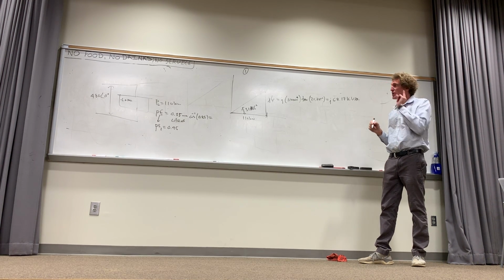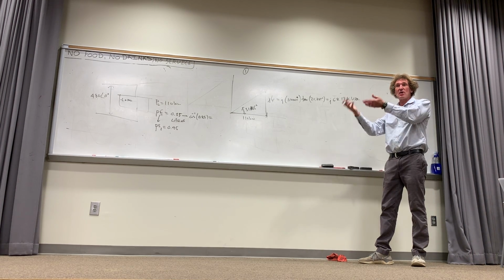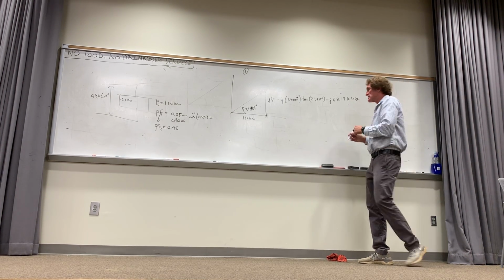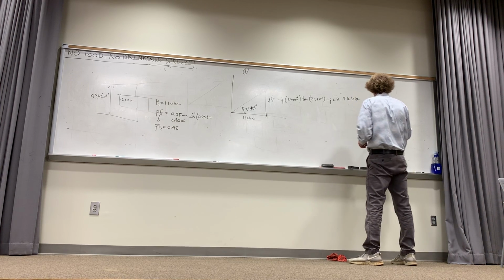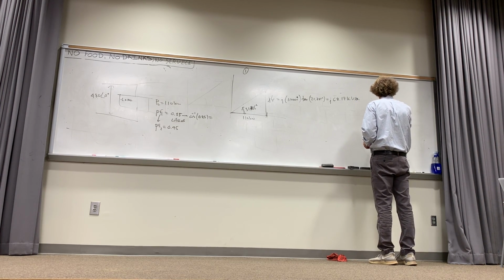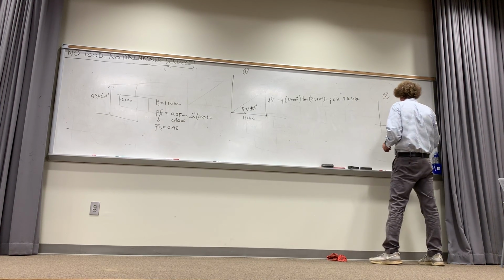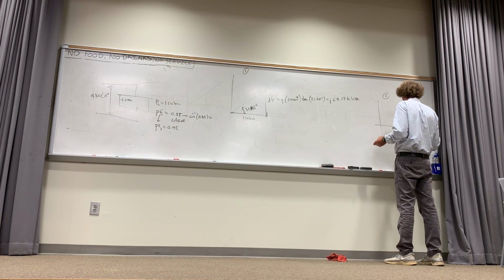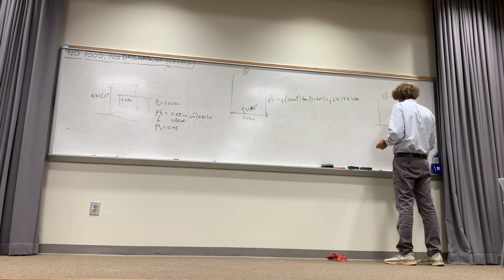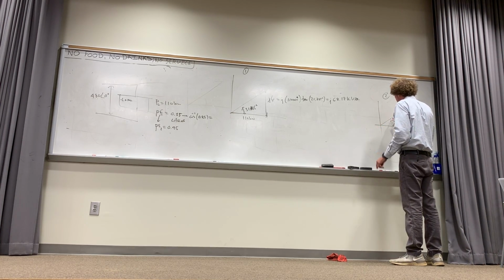That's what I started with, right? Where do I want to go? The resulting thing I want to get is this power triangle, the second one. I want to have the same real power. You can never change that. The real power is still 110 kW. But now this angle changes.